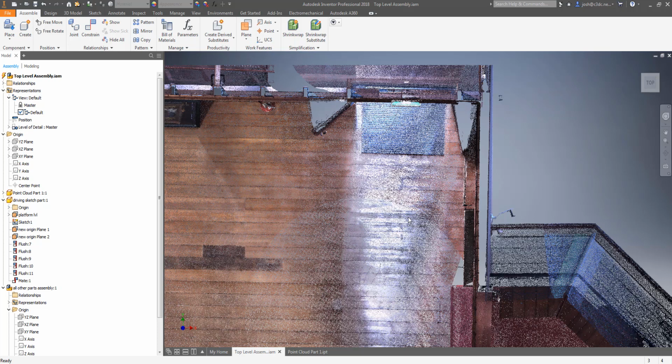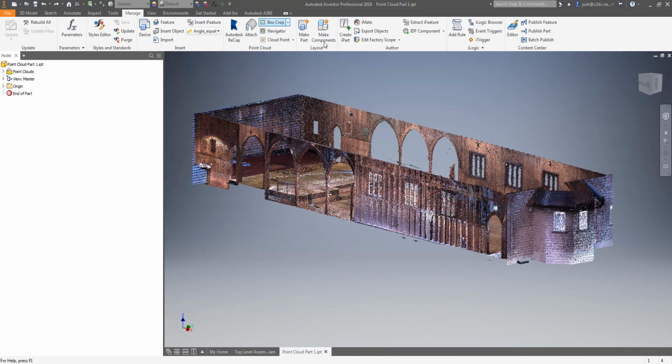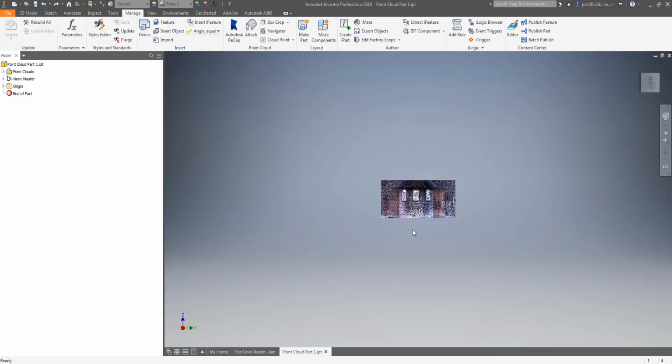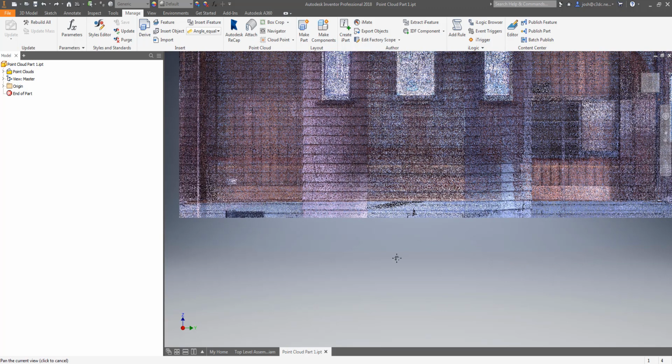If you are struggling to see the detail that you need in your point cloud, try and find out from your scan service provider how they process the point cloud and if it's possible to get another point cloud that has more detail. Due to this, you need to find the balance between an appropriate zoom level and a reasonable amount of detail. You will find that taking a little time to crop your point cloud to only show the detail you're interested in tracing is the best approach here.